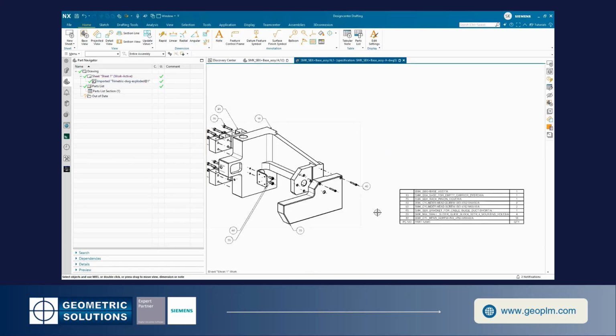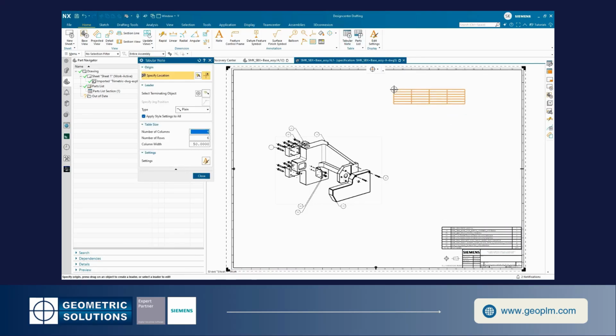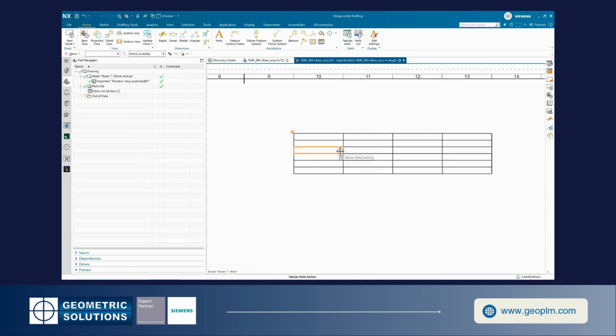So now I want to show not only the build of material, but also the balloon callout. Right mouse click on the view, then we can add that directly into that. The next thing we want to do is create a revision block. That is a very typical behavior of a drawing, that we have a revision block.